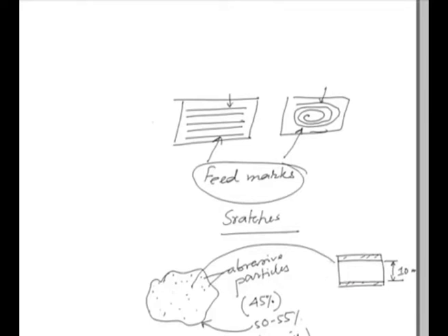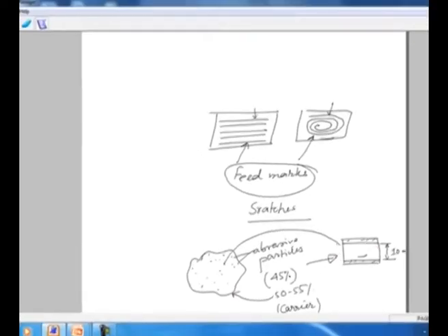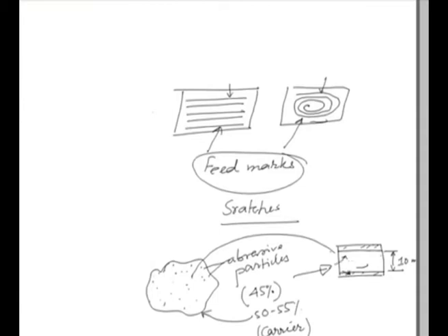that is fixed on this tooling, and the media is allowed to move through this. While moving through, the media will come in contact with these surfaces which are to be machined or finished. Now, in fact, these tiny abrasive particles, which are very small in nature, will scratch this surface, or we can say plastically deform it, and at times they will remove some of the material in the form of tiny chips, and in the process this surface will get machined or finished.